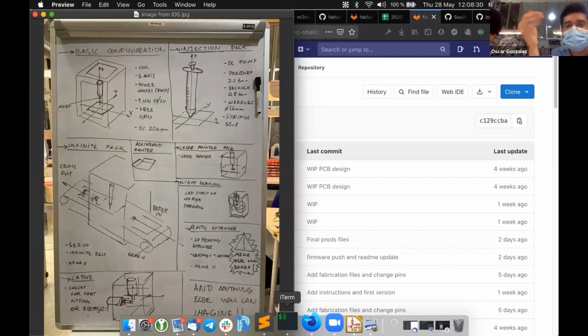Meanwhile, in these systems, you need to send the command and keep asking at which position you are in. So you can stop or brake one of the motors so it keeps the real position that it needs to be. It's not a closed loop system, but the integrative part on the estimation of the positions, speeds and acceleration is much more complicated.